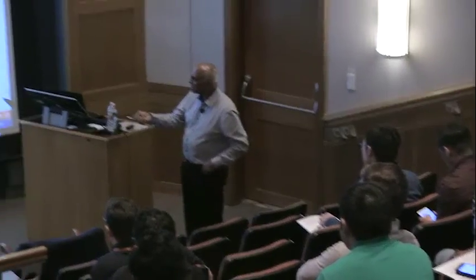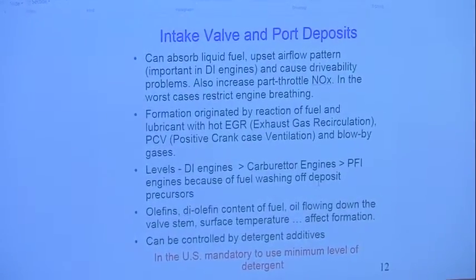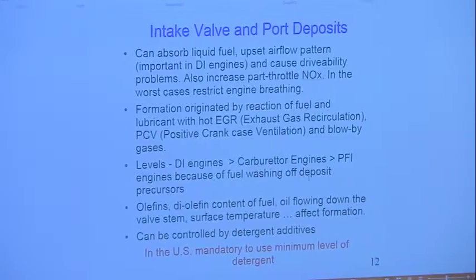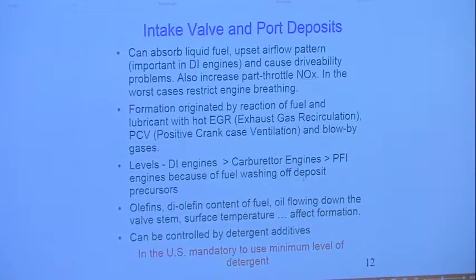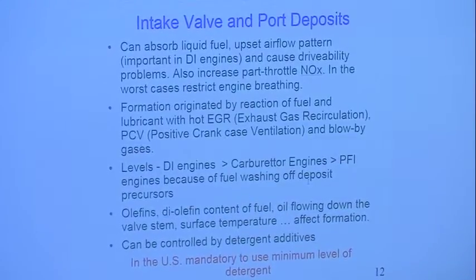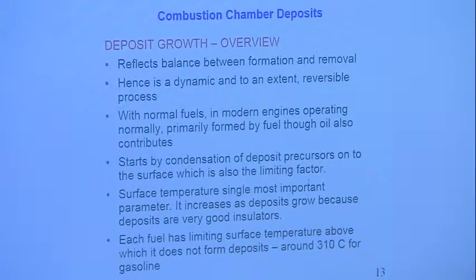And things like olefin and diolefin contents, there are a lot of empirical tests done. There is a lot of data on what kind of fuel properties matter in producing deposits. But they can be controlled by detergent additives. And as I said, in the US, it's mandatory to use a minimum level of detergent. Right. Combustion chamber deposits.